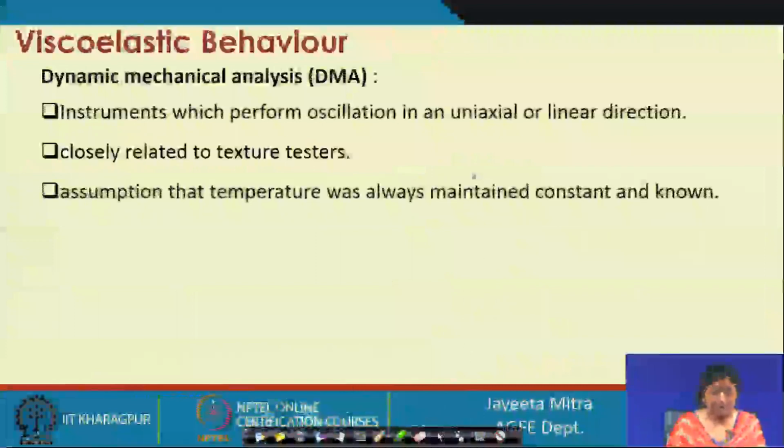As I said, textural behavior can be observed from that. The assumption over all the analysis we are considering so far is that temperature should remain constant, because temperature has a significant role in viscosity as well as in deforming or breaking down the molecular structure of the material.